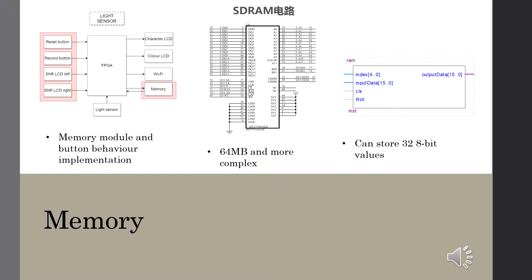My memory module design contains only 5 ports. 2 separate ports are used for input and output data. One is for the address, while the other 2 pins are used for the clock and read-write pin. When the read-write pin is high, write mode is activated and the memory stores the input data to the specified address. Likewise, when read mode is activated, then the output data port outputs the data stored from the given address.